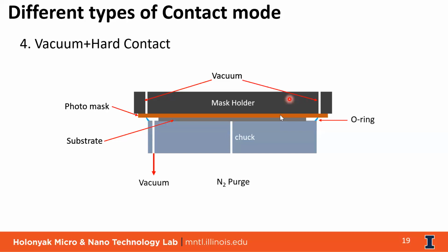Yeah, basically you can do it 1:6 or 1:10 ratio. So we can mix it at our lab, H2SO4 and hydrogen peroxide at 1:6. We'll use it. Plus, you don't get Piranha ready-made available, but there are some companies providing ready-made mask cleaning chemicals. So if you do not want to use Piranha, probably you can purchase it from them.